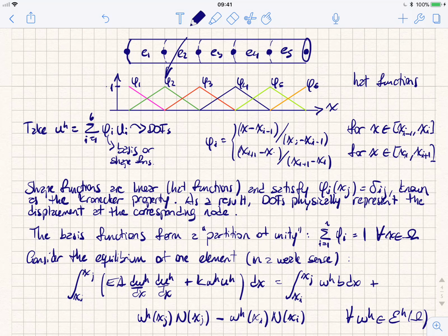And this is also a very nice property of finite element, because what you would expect is that if those functions are only local, the resulting system of equations is very sparse. And sparse systems of equations are good. Okay, you can solve them fast. This is another nice property that does not happen if you take, for example, the Rayleigh-Ritz method, where your functions are acting globally, so the system that you get is not sparse. Okay.